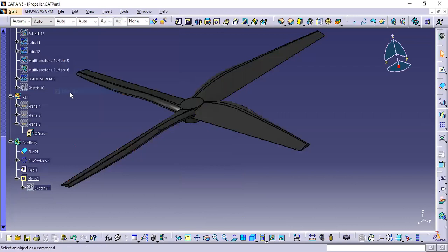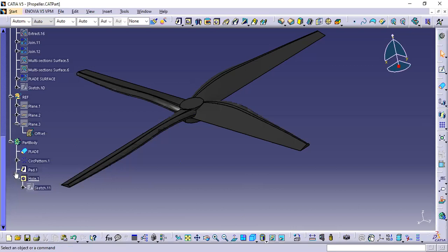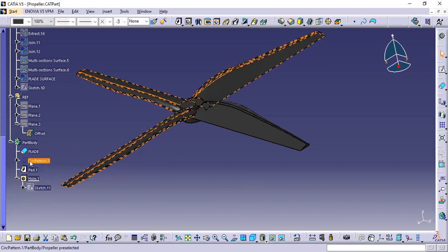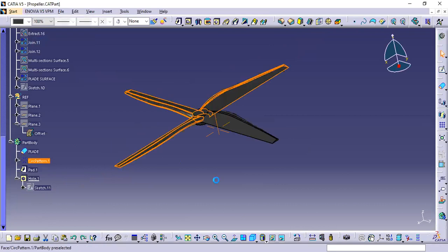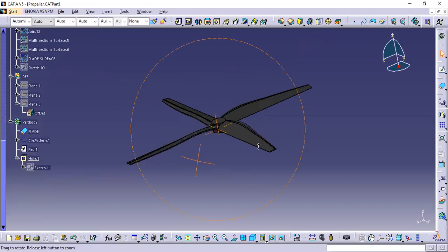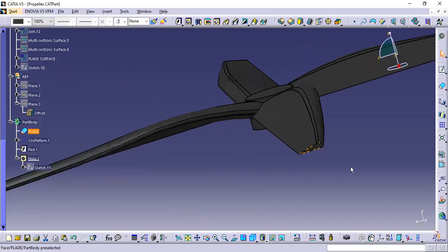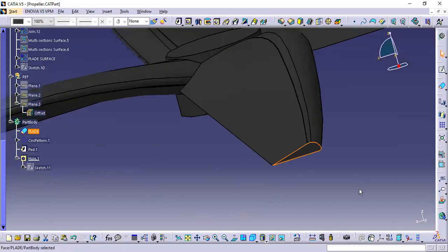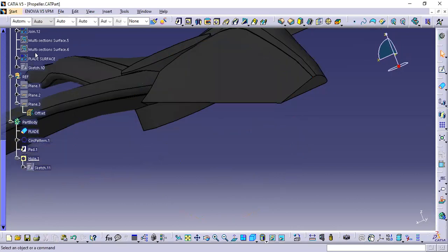Let's hide them. Yep, but we colored it in black. So as you can see, this is a 3D model. After we closed it, we used the closing tool, which is this one here, close surface. It created a 3D solid out of our 2D surface.